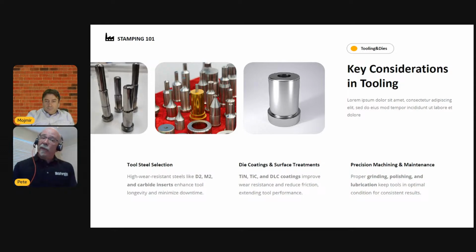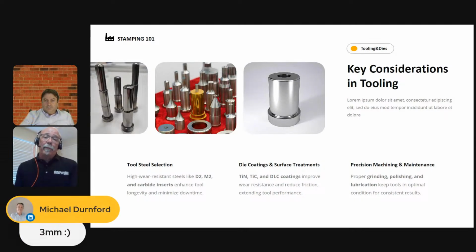Well, we started removing a lot of material at once so we can hurry up and get that ground down. In the process of doing that, they changed metallurgically the structure of that punch. At the end of the presentation, I'll have a micrograph to show you what's happening. We've actually reheat treated the very top portion of the punch. The surface underneath where we just heat treated, we actually tempered it. It's annealed, so it's softer. And then as we get to the body of the punch, it's the proper temperature.